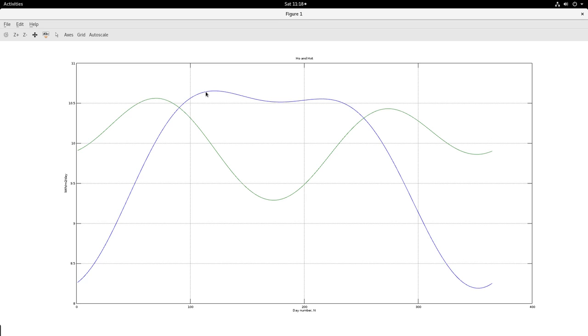So the max energy minus the min energy here, the ripple, that will be the delta H ripple, is large in the case of the horizontal flat plate collector compared to the max energy minus the min energy of the tilted surface. Therefore, it becomes essential that we tilt the surface appropriately at a proper angle, such that you get the best collection of energy from the sun. We will see shortly what would be the best angle beta of tilt that we should provide for a given latitude.